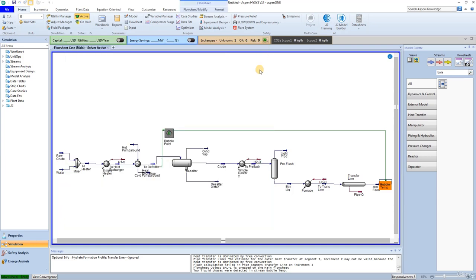The adjust operation is another logical operation, a mathematical operation rather than a physical unit operation that models a piece of processing equipment. It will manipulate the value of one stream variable, the independent variable, to match a required value or specification, the dependent variable, in another stream or operation.